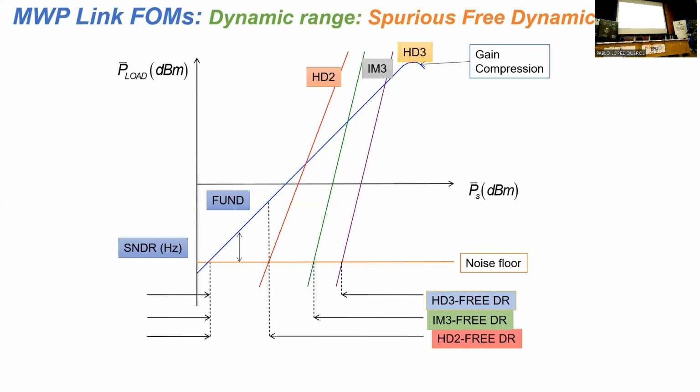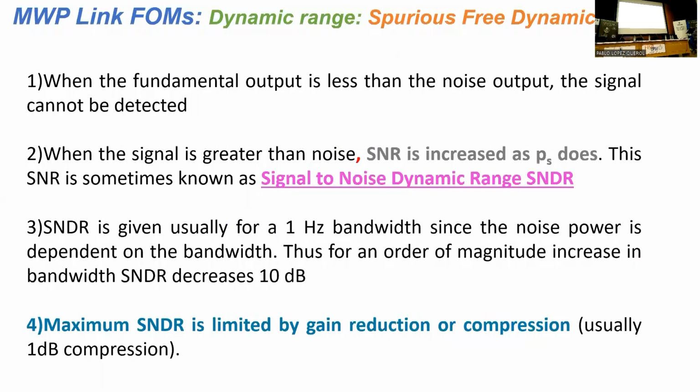In most practical systems, second order intermodulation is not very significant, because you will have all your channels inside one octave. So all your relevant intermodulation is going to be due to third order intermodulation.